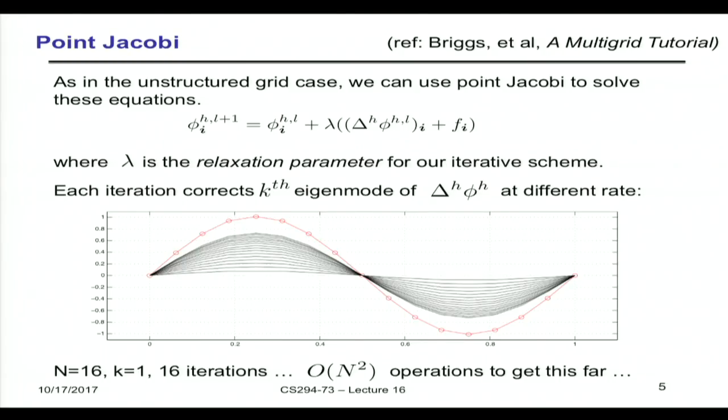So if you've studied time integration schemes, you know that for a big enough time step, it'll blow up. It's unstable, right? So we're going to talk a little bit about the Fourier analysis here to ask, what do we need to set lambda 2 to get the effects we want? We could set it to 0 and never make any progress. We could set it to something too big and it'll blow up in terms of your iteration. So somewhere in between is the magic number, and a lot of what we're going to talk about today is what those magic numbers are.